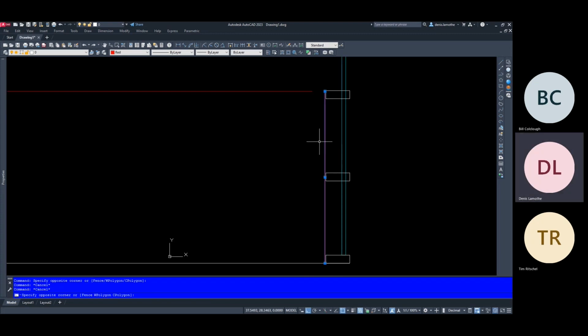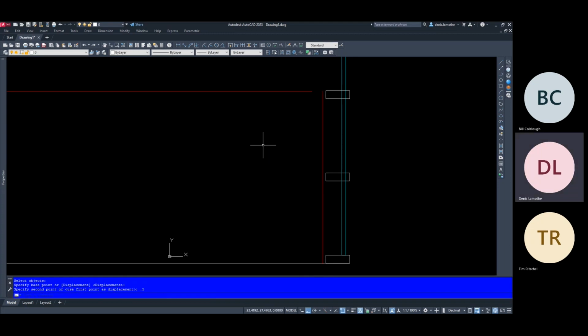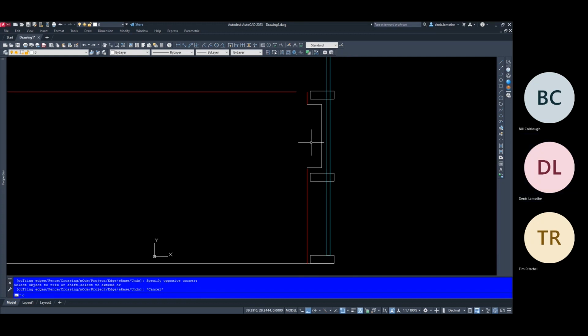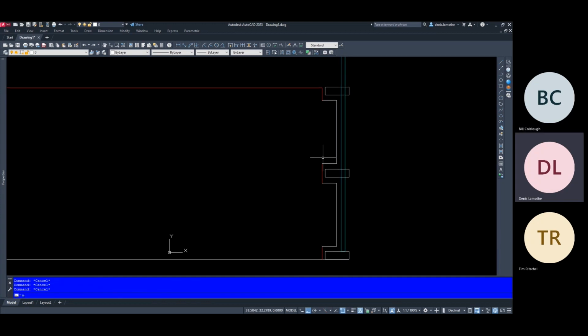So this may be a situation where, if that occurs, and I'm using a curtain wall here as an example, it could be something else. What I would want to do then is notch the glass panel so that it follows the profile of what we're contouring around, just to make sure that we maintain that 4-inch maximum opening. Sorry, I'm bad with my words today.